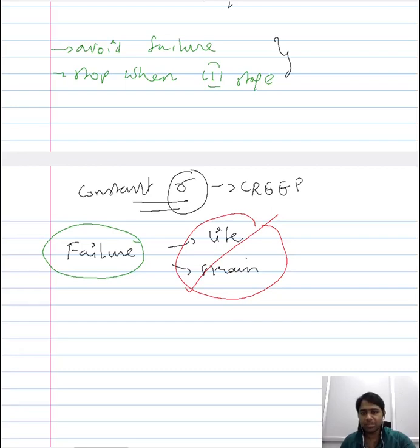So the important change that we make is again associated with the stress, as it is the stress that prolongs the duration of this testing when you have a normal creep consideration. It is the constant stress that prolongs the overall test duration when you allow the material till it fails. So in this particular test, wherein we want to focus on the failure of the material, the stress that is employed is varied.